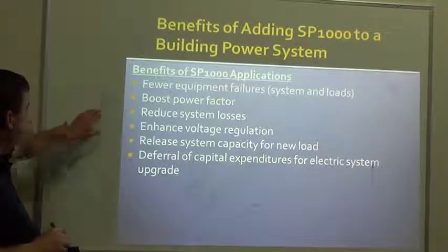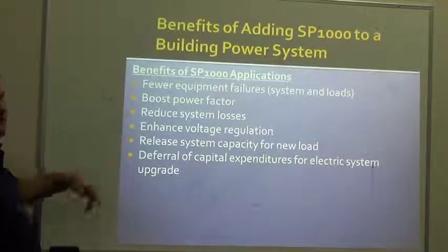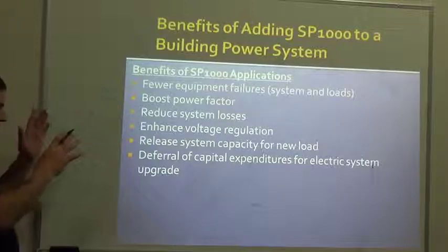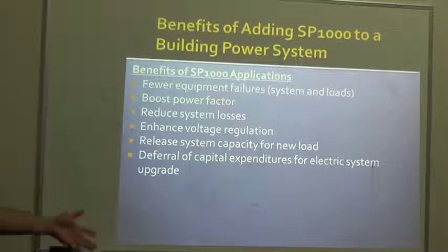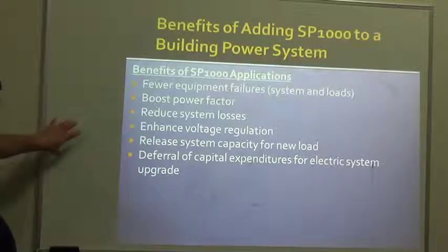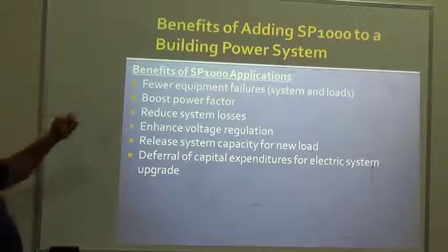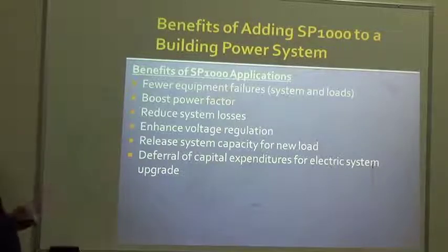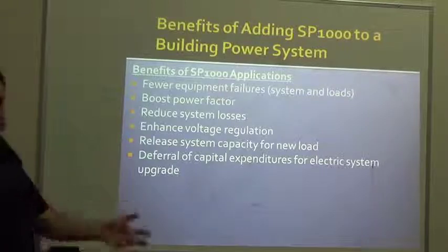But you have to figure out what their reactive power situation is, which means you have to look at their bill, and look at embedded data in the plant, if that's available, to get somewhat of an idea about how the addition of this to those buildings is going to affect their overall reactive power situation. Because it will push it in the wrong direction, but the question is how much?